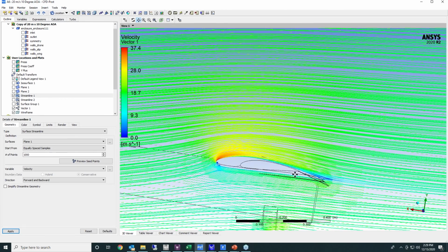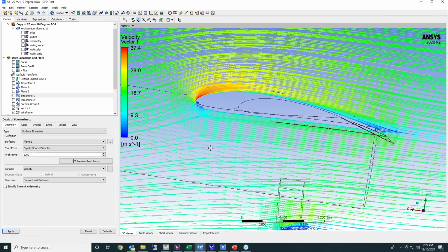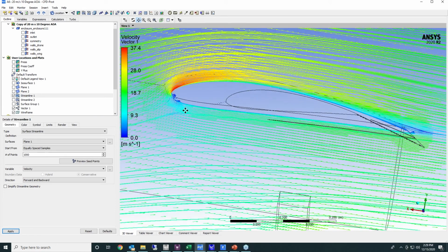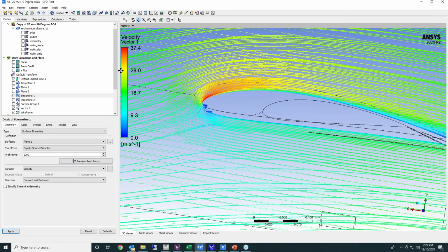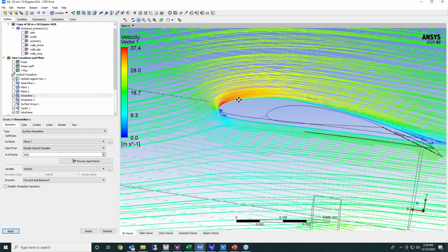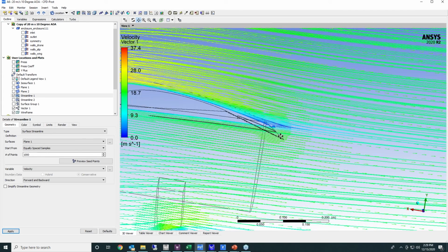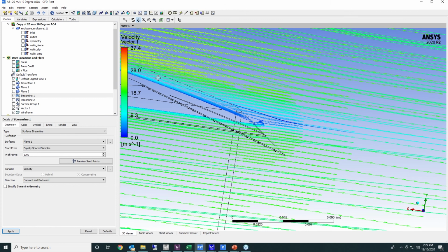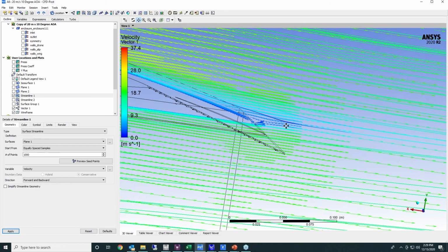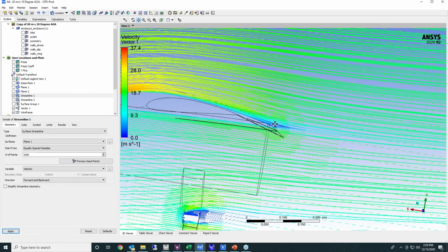Okay, so basically we're looking at that plane and air is coming up, it's hitting the wing. You can see I get a stagnation point here where these velocity vectors basically go down to 0. Here's my scale for speed, and my streamlines and velocity vectors, they quickly go over the top of it. This is where I'm getting my highest velocity, and this is where I would expect to get some of my lowest pressures, right where the velocity goes the highest. And that would give me lift because I'd have higher pressure on the bottom of the wing, lower pressure on the top. And then at the exit of it, you can see that you get somewhat of a separation here. It's not quite a recirculation zone, but you do get some separation here at the trailing edge of the airfoil.